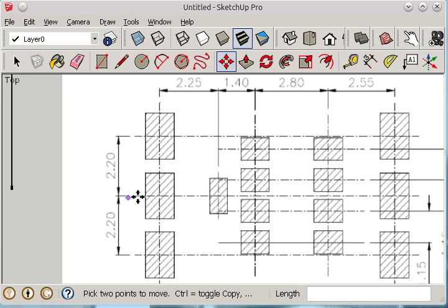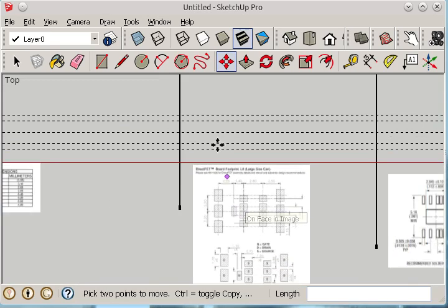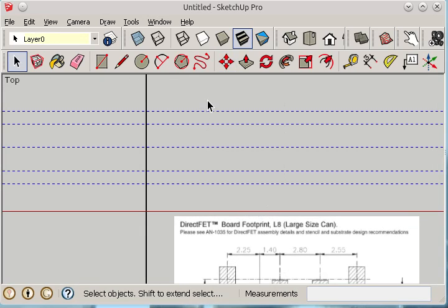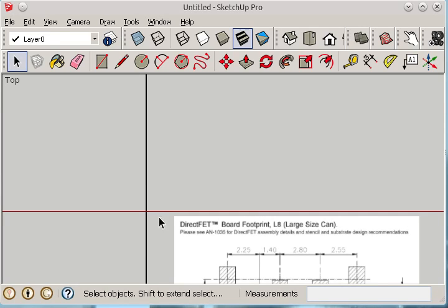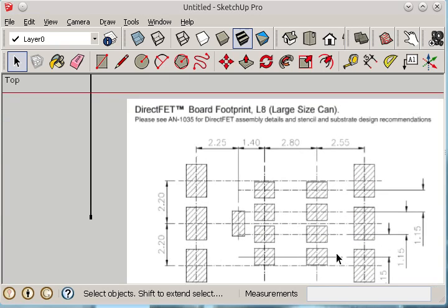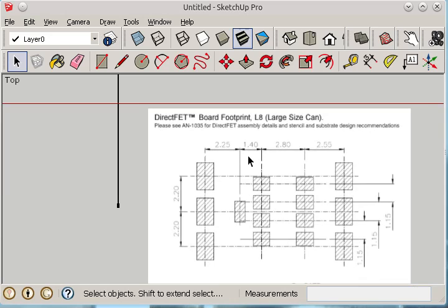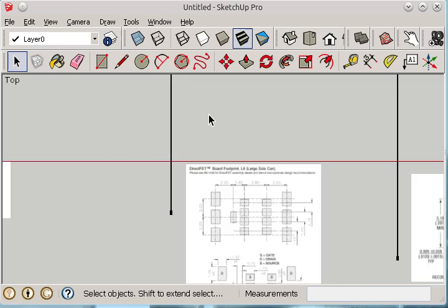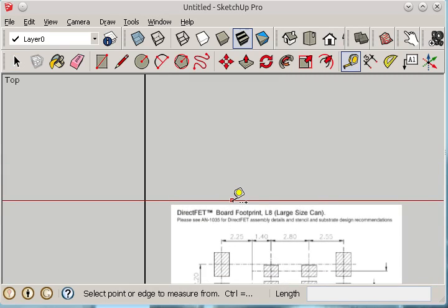I think we draw a construction line, the symmetry line here. This would be helpful. I delete the construction lines from the other footprint. Here I have drawn a copy of the green axis, so I can draw construction lines from here, or in parallel to the green axis. So let's start with the symmetry axis. Press T for measuring tape and place a construction line here.